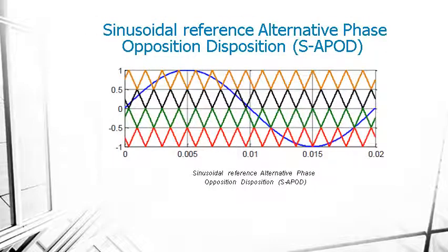Sinusoidal reference alternative phase opposition disposition, SAPOD. This figure illustrates the sinusoidal reference alternative phase opposition disposition technique. In this technique, each carrier of the method is shifted by 180 degrees from its adjacent one as shown.